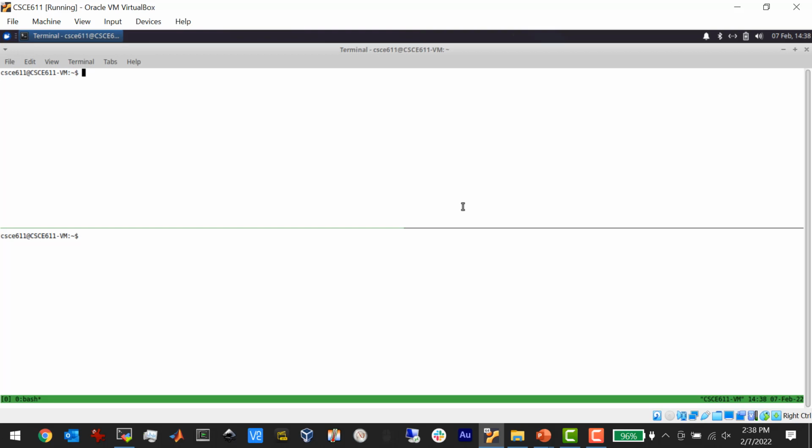So instead of having to directly interact with hardware with your code, you could do it through a function they provide, basically. So instead of having to tell the UART controller, all right, UART controller, set up for 57,600 baud and 1 stop bit, you just say printf, and it goes through it because the printf is implemented by the HAL, the hardware abstraction layer, right? So it simplifies things a bit. You don't have to use it. You can just write code, you can just put machine code on this thing if you want.